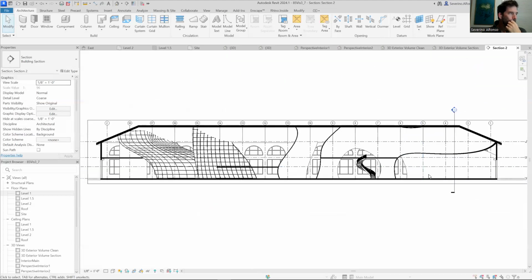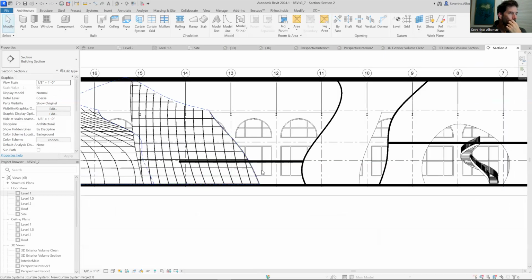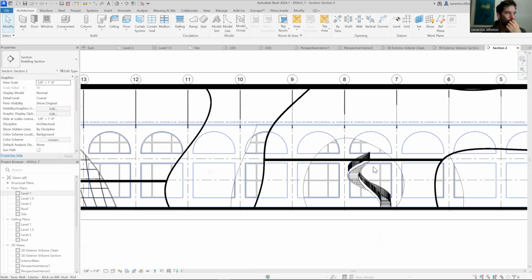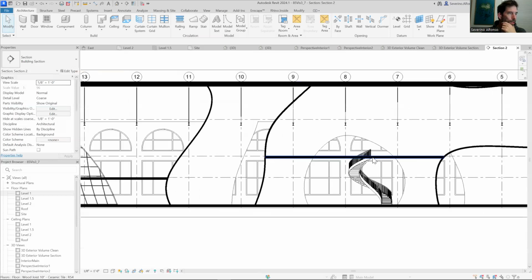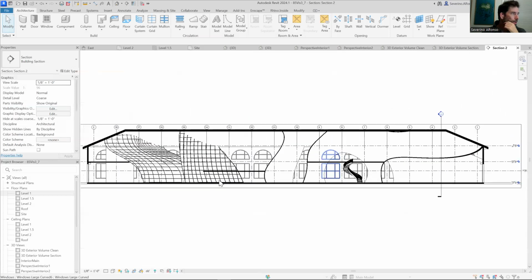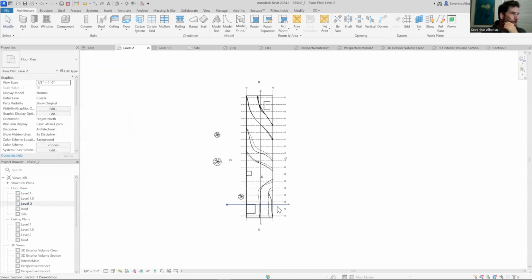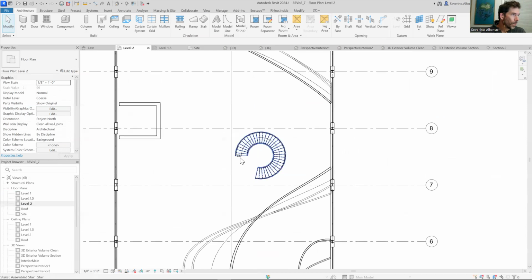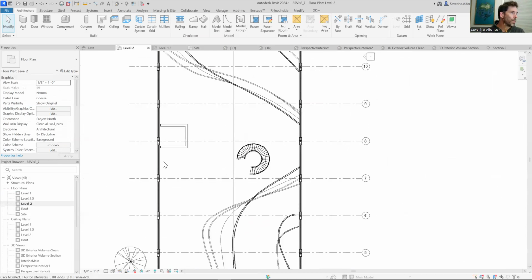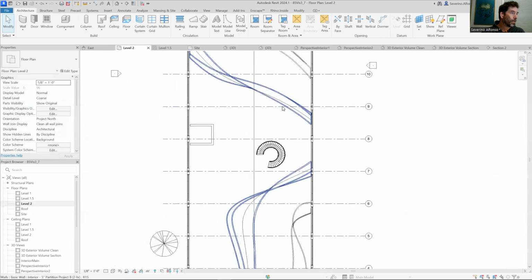That's great. I'm going to then do another stair here in a different way. So obviously, if we go up the stair, we hit the floor. So that's not a great idea. So let's go to level 2 and wireframe, WF, to see where we want an opening. So the ideal place to create an opening would be in the floor of level 2.